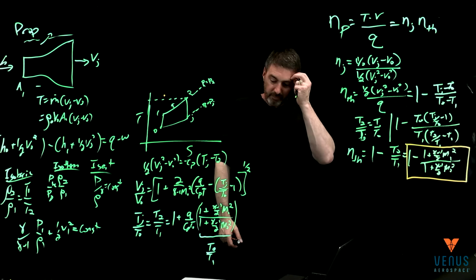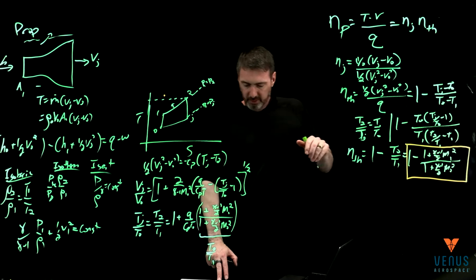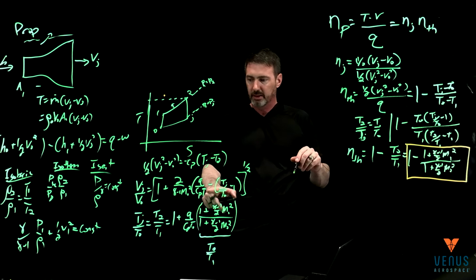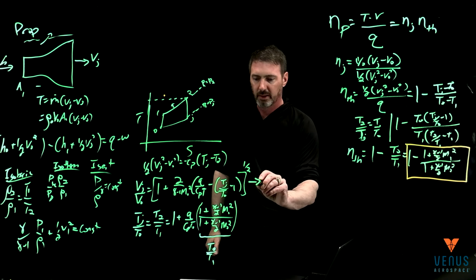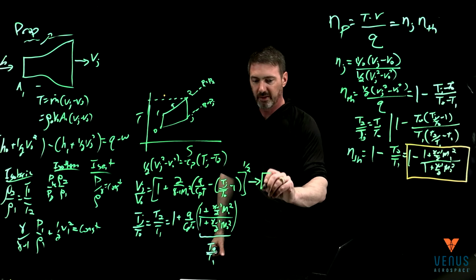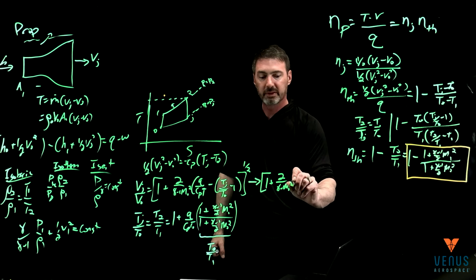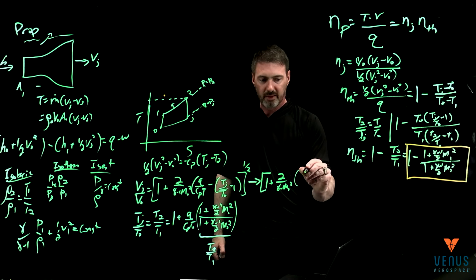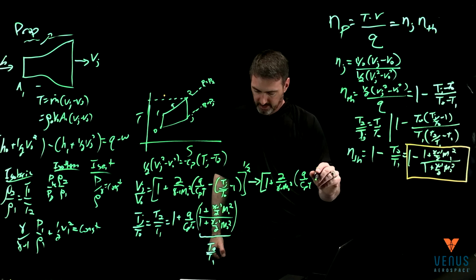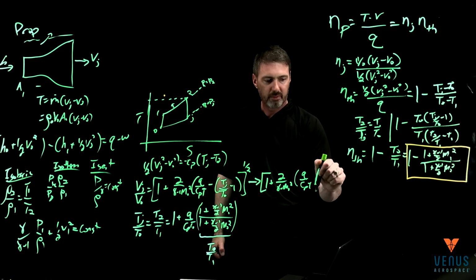All right. And then once we have this thermal energy, we can come back to this equation here, because now that we solved for the thermal efficiency, this actually has a much easier form. So 2 over gamma minus 1, again, free stream Mach squared, and then this is just Q over CP T0 times, and let's get rid of that.